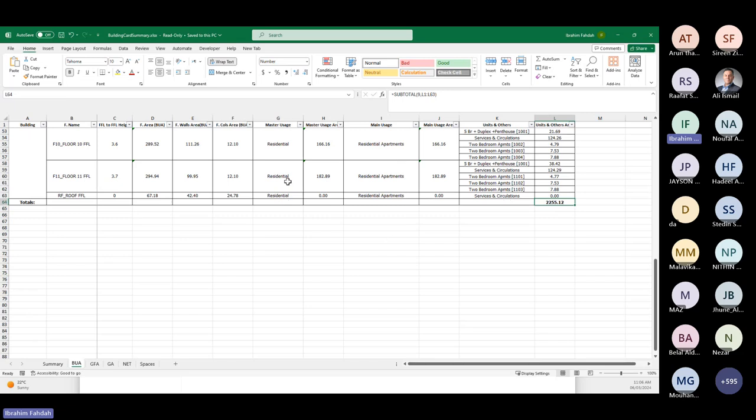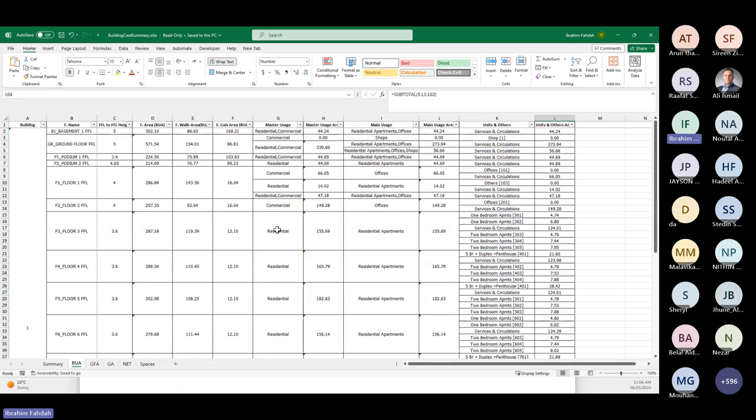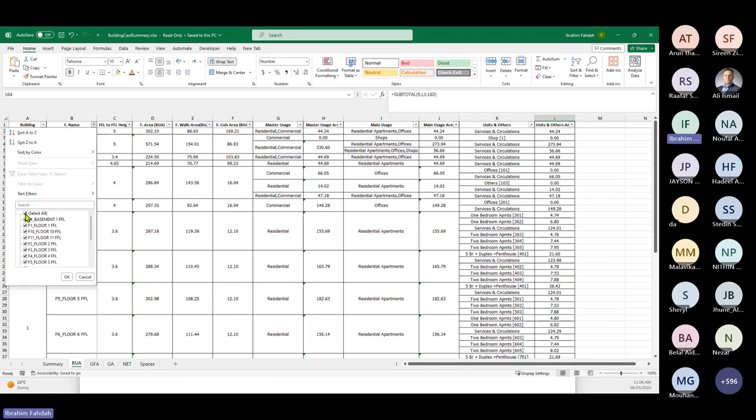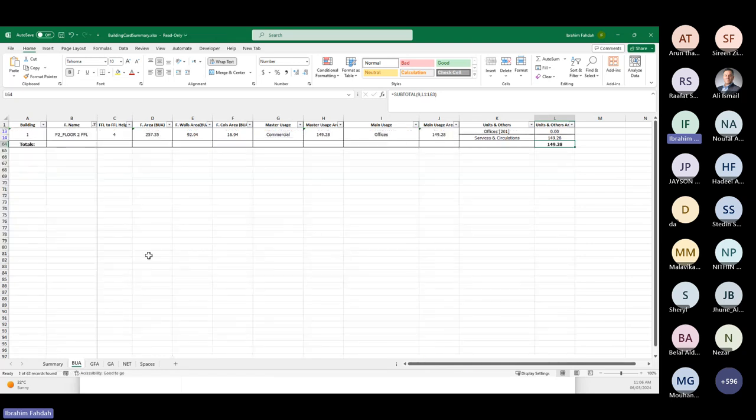But what we provide you with is an auto-generated building card based on the information from your BIM models. If you have big differences between your hand calculation and the number produced in here, for every space and every floor, you can filter in here. So you can find the total built-up area. In this case, I'm on the built-up area per floor. And because I'm in Excel, you can do all this automation and summation in Excel if you're interested in accumulating different types of area.